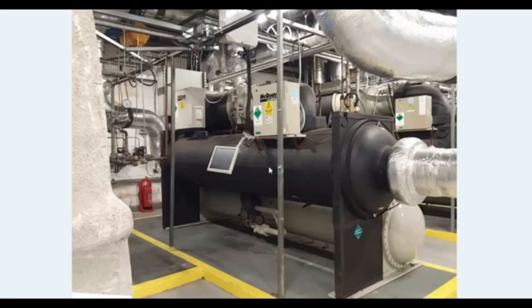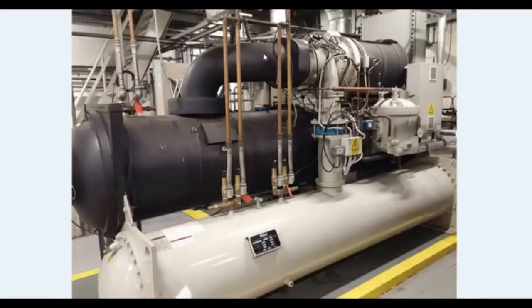evaporator, and that allows it to pick up a bit more heat where it passes through this tube at the back there, passes through here, enters into the compressor. Remember, this on the back again is a large electrical motor which is forcing the compressor to spin and push that refrigerant all the way around the system. And meanwhile, the chilled water is entering and leaving here. It's entering at about 12 degrees and it's coming back out at about 6 degrees Celsius.